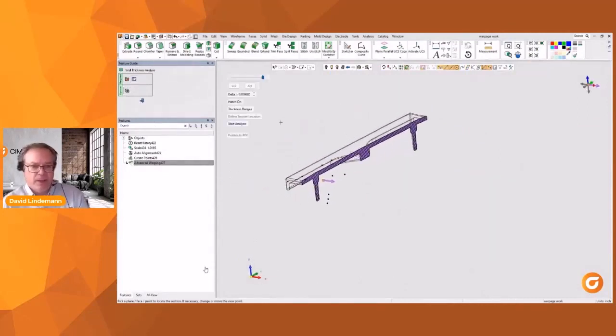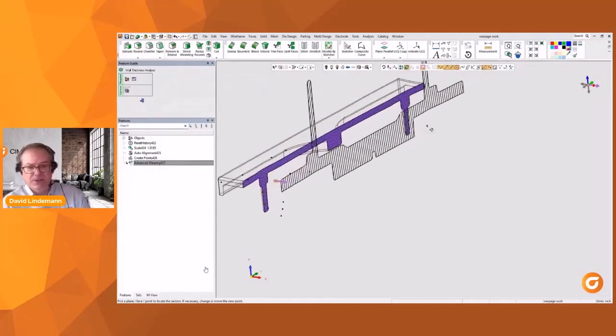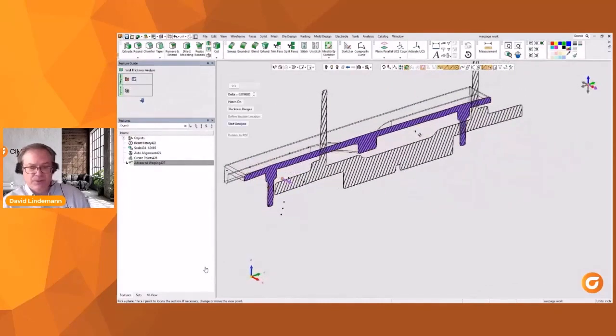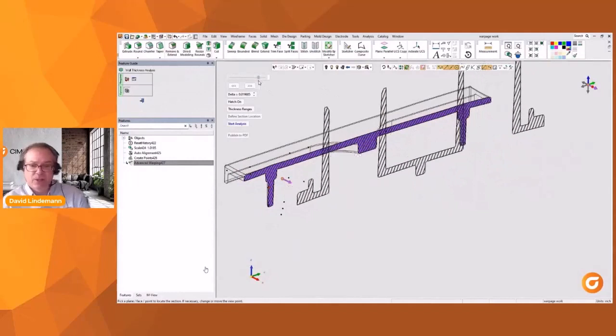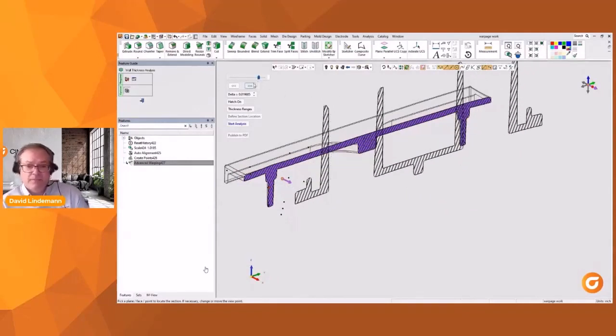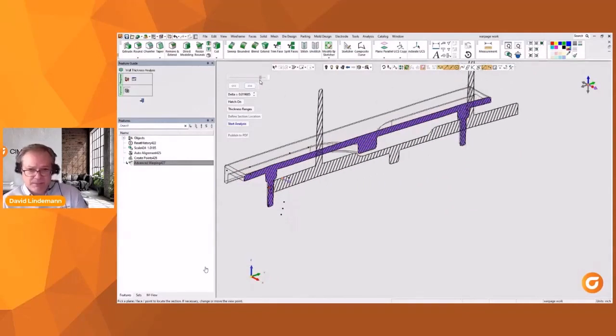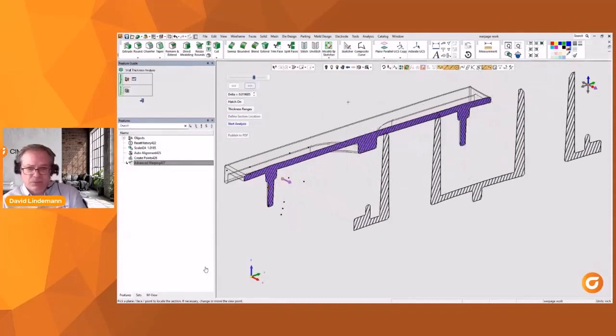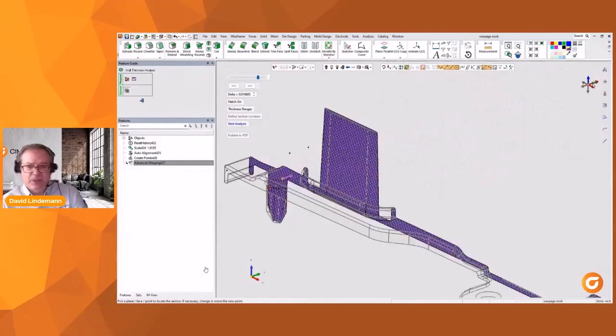Here is another great way to understand what is happening with the wall thickness. Am I consistent from front to back, from side to side? Well, we can cut this cross section. Along the cross section, I'm seeing the warpage. I can see that the bottom's not perfectly flat. Okay, so definitely it's there. But at any position I see it's important, I can go ahead and snap that and then take a look at it in greater detail.